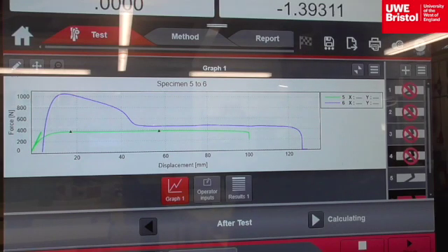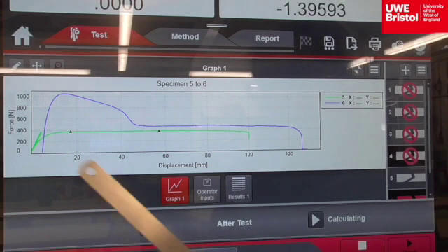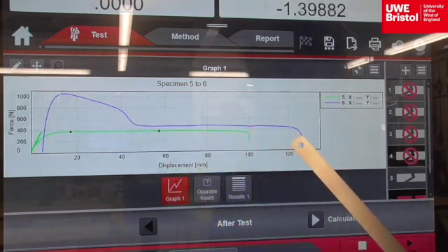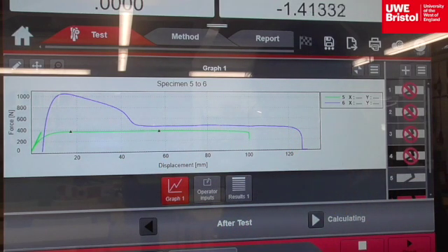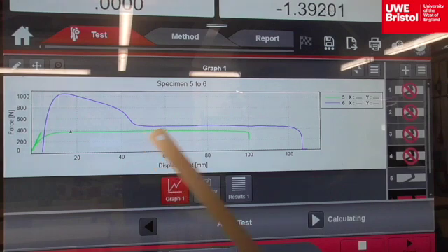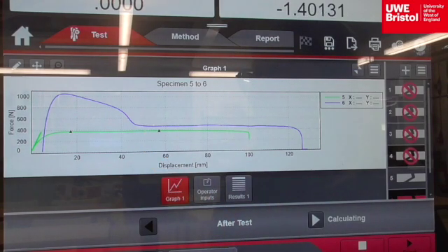Looking at the two plots where green is low-density polyethylene and the high-density polyethylene is in blue, high-density polyethylene is a much more organized structure. Up to 80% of its structure is crystalline, meaning there are a lot more cross-linked bonds between the long parallel molecular chains. The low-density polyethylene has up to only 40% of crystallinity.